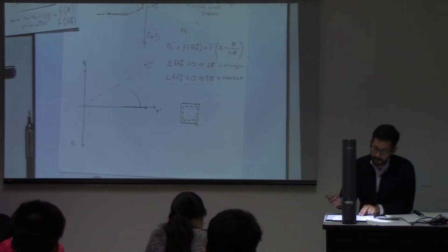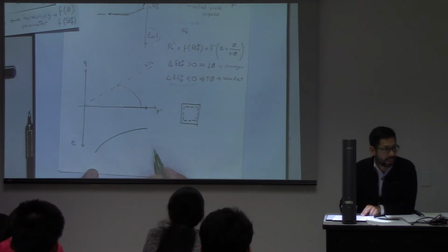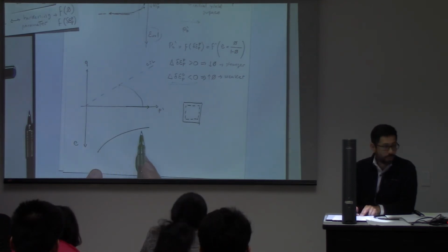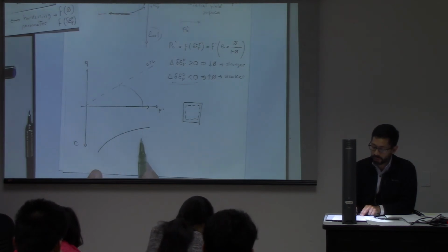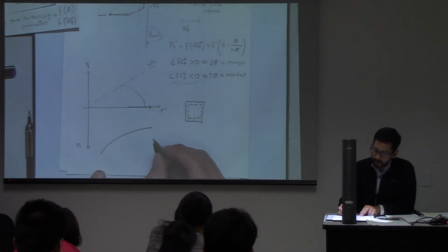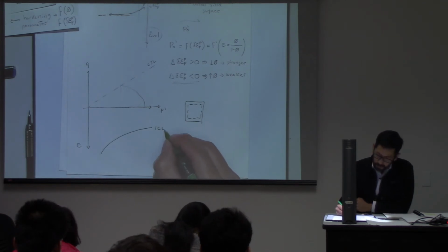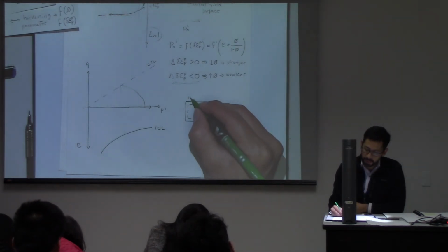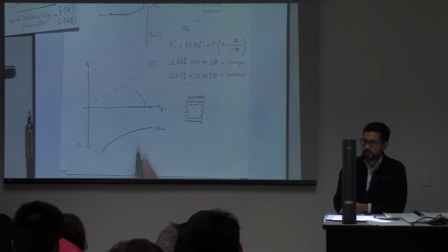And what that means is that that line, if it's in linear scale, is going to be a curve. The higher the mean stress, the lower, notice that here I'm going lower in porosity or void ratio. And this is what is called the isotropic consolidation line, or ICL. It's an isotropic test, and it is nonlinear, okay?